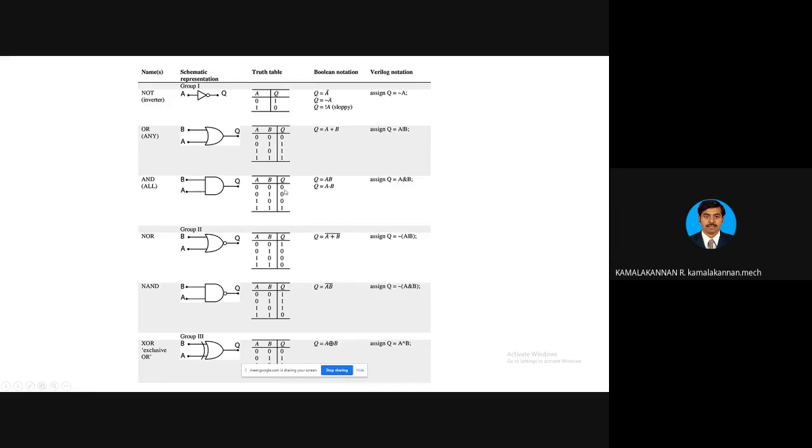See here, once you have a signal in both inputs A and B, you have an output. So the reverse of that will be the NAND. For all other conditions you have a signal. You will not get a signal only when you have a signal for both inputs A and B. So that is what the NAND gate is. Q equal to A B whole bar.